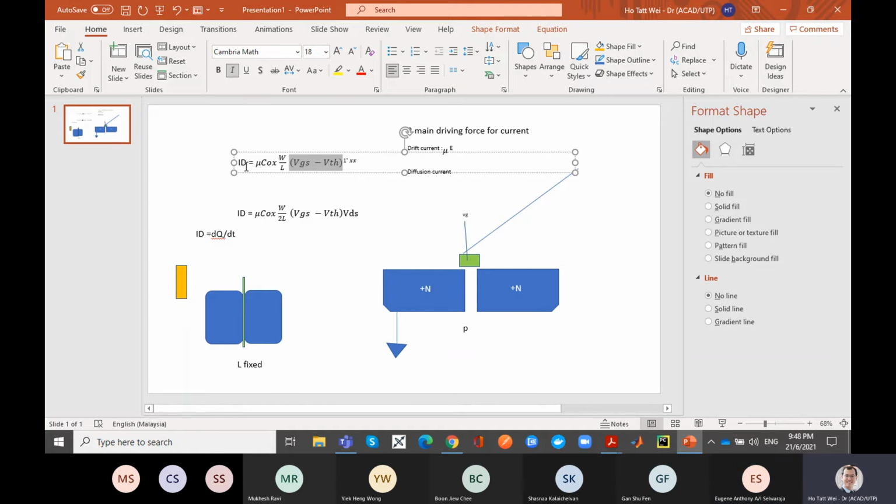You change the threshold voltage a little bit, the current will change by quite a lot. And also the leakage current, not just the current, is sensitive to the threshold voltage, because later on in module 4, module 5, you will see that VTH is one of the transistor parameters that can change quite a lot during production. During fabrication, there's quite a lot of variation on VTH.